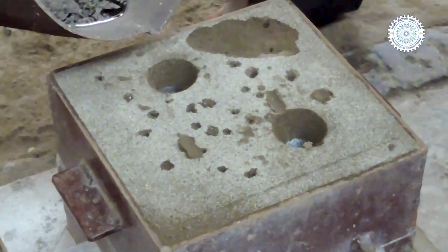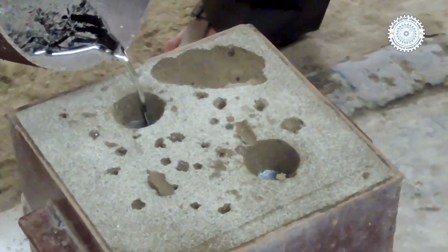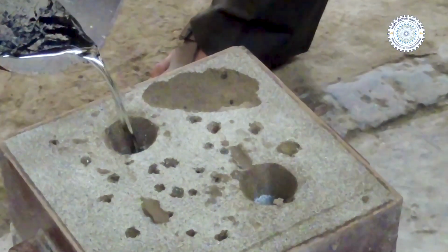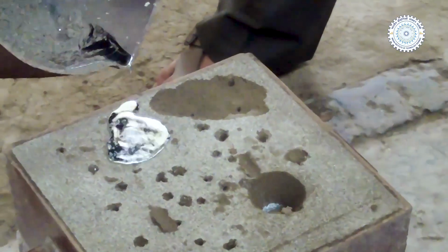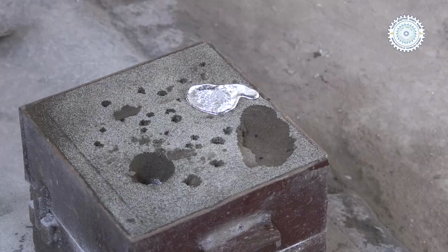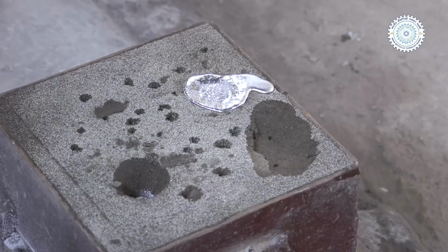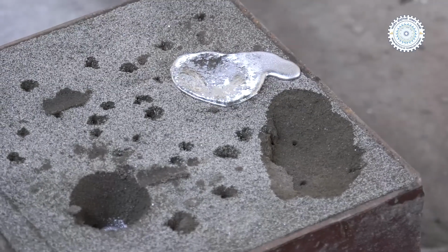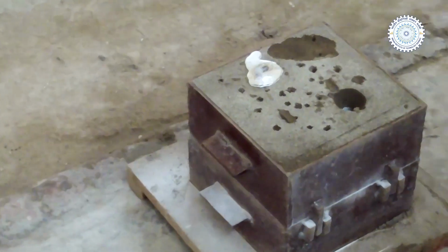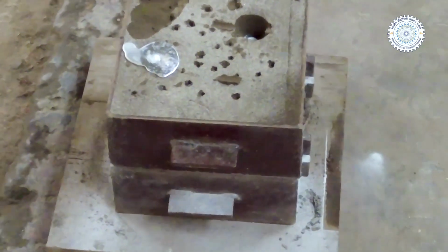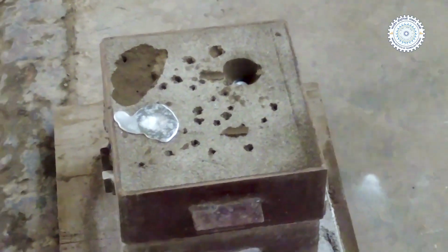Now molten metal is being poured into the mold cavity through the pouring basin. It goes into the sprue and into the mold cavity. You can see a riser is also being filled. Now the molten metal will solidify since heat is being absorbed by the mold wall and entire mold, and we have to wait for solidification. Once it is solidified, you need to break the mold, and you get the casting.